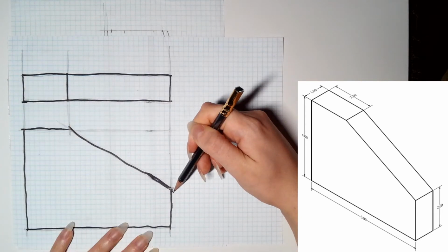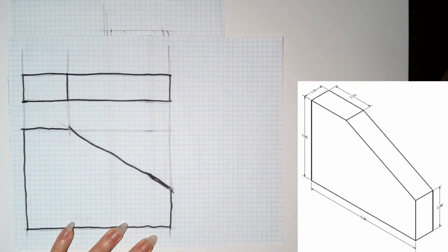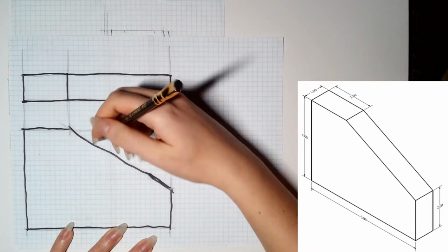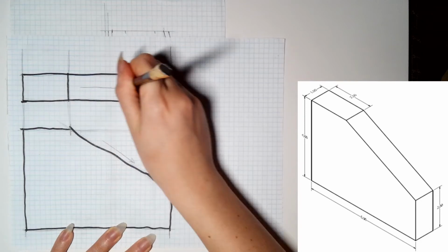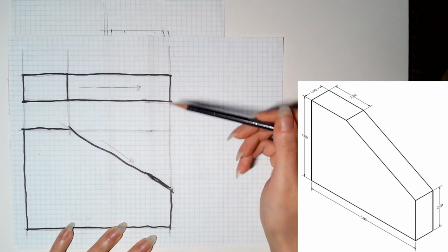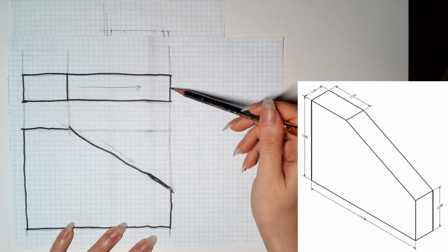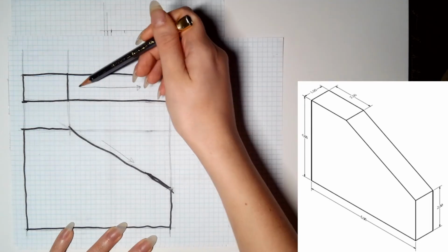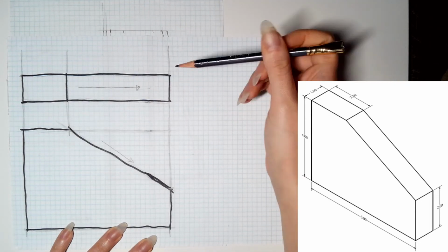And that's because objects that are slanted are going to appear as foreshortened in an orthographic view. So we have this slanting downward. This also is technically slanting downward, but if I'm looking at it directly from the top, keep in mind the top isn't showing me anything related to height, I can't see how far down it slants when I'm looking at the top view. So it's going to appear foreshortened.